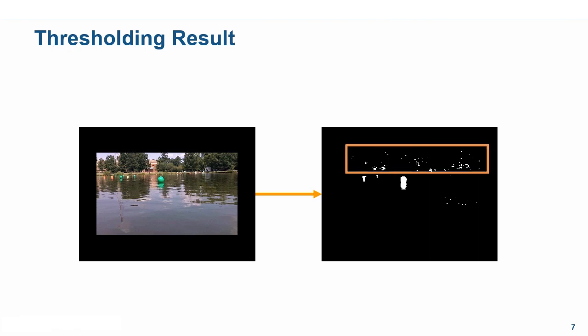Here we see the result of the thresholding. Notice how there is noise in the image. Thresholded binary images like this sometimes contain various distortions, such as the noise here. Blob analysis can remove most of these disturbances, but noise close to the area we would like to detect will still remain unaffected. We can remove these disturbances before performing blob analysis using morphological operations.